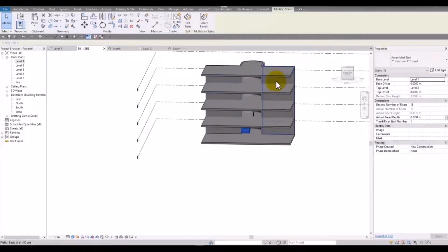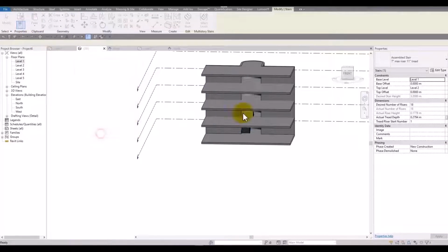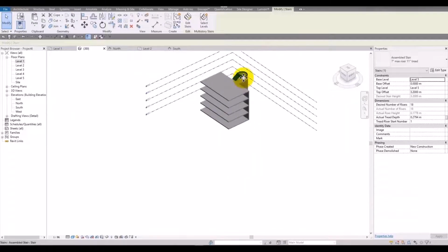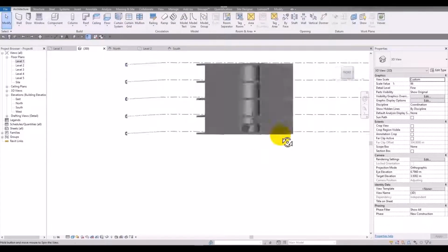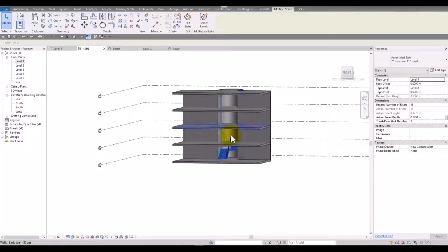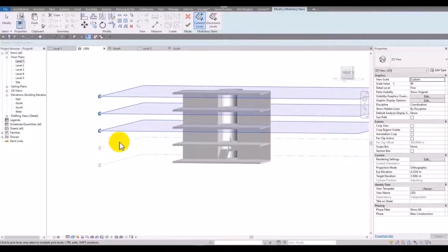And to duplicate the stairs, we can copy here, and level 2, 3, 4, 5, which the base will be at level 5, so it's like this high. Okay, that was a way, and another way is to making a group with them. How? We select the stairs, then select level, and then we select the line of the levels which we want to have the stairs in them.